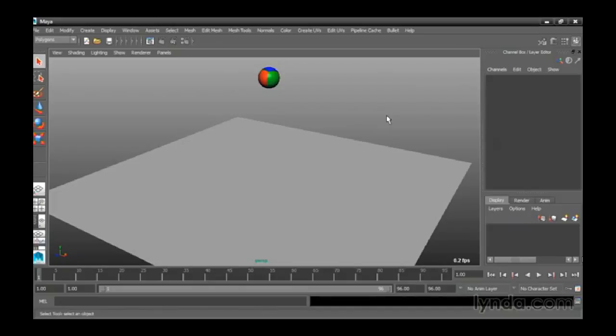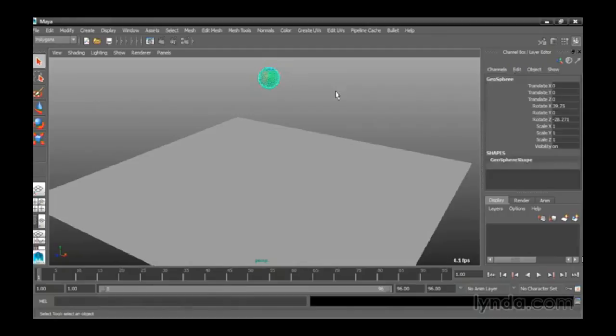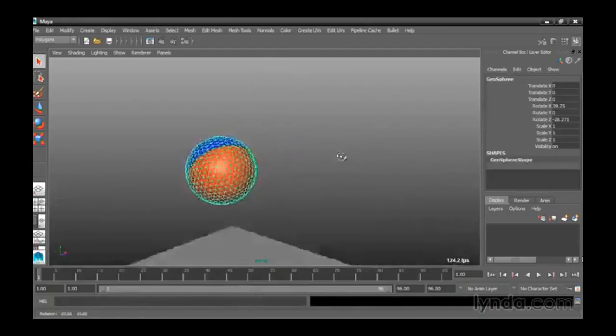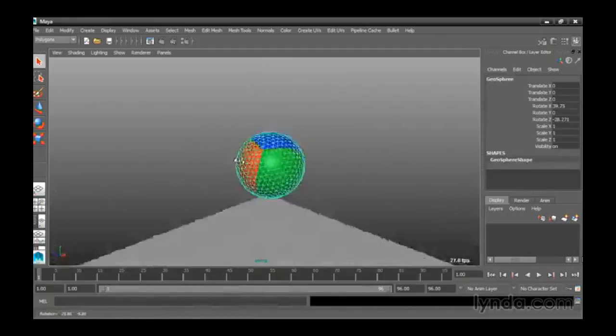And I couldn't really achieve that with Maya tools because a standard sphere is going to have poles at the top and bottom. And you could try using an icosahedron and smoothing it, but once again, the polygons will not all be the same size and they will have strange poles on them. What I did end up doing is using the 3ds Max geosphere primitive. Take a look at that. I'll select that ball and press the F key. Tumble around so you can see that all the polygons are the same size.